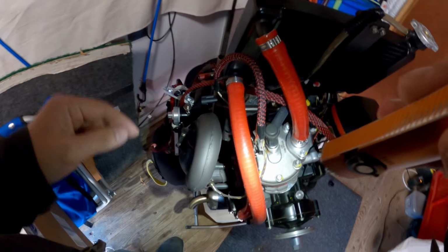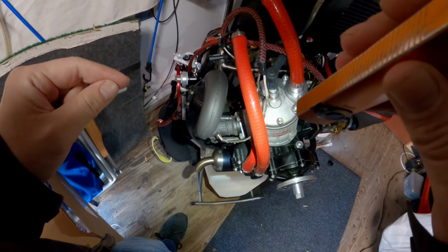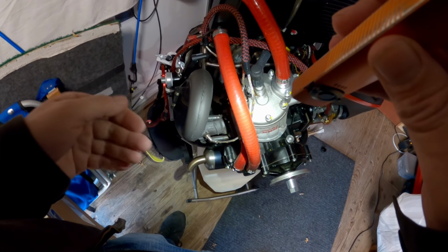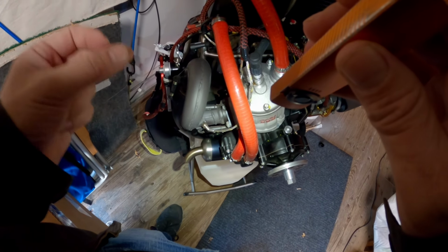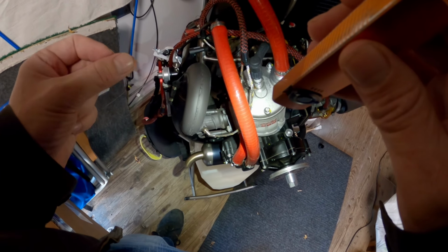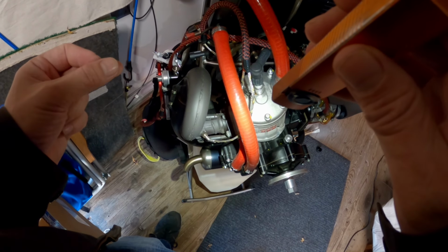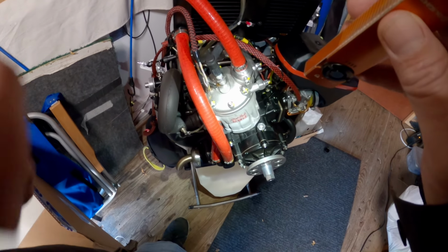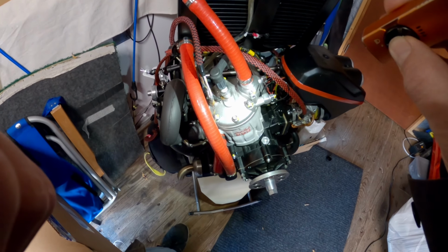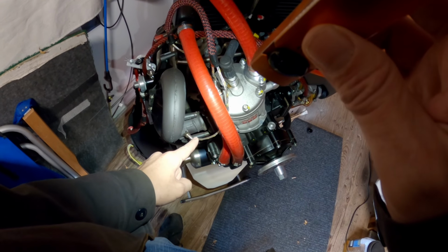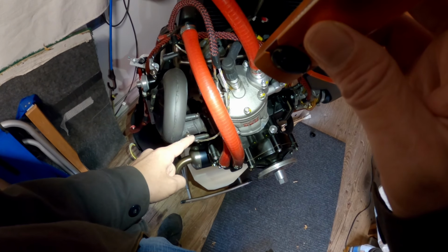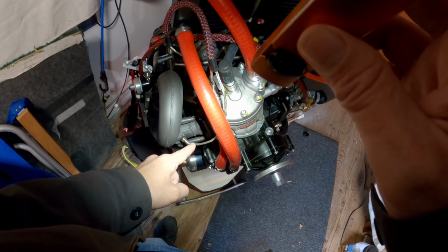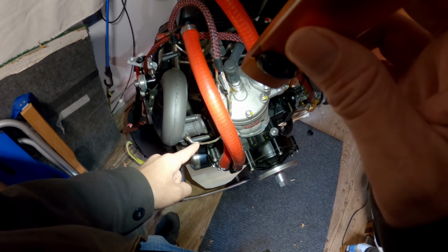Having an oxygen sensor gives explicit information on the air-fuel ratio. As far as what the optimal air-fuel ratio is for a two-stroke, I don't know yet. What I've been doing is targeting stoichiometric, the optimal air-fuel ratio at idle and cruise RPMs. I'm learning by doing and just finding out for myself. Then if we look at the EGT sensor, this is where we can infer information about how it's running. And the bonus that the oxygen sensor doesn't have is that this can help you optimize timing to a certain degree. Pun intended.